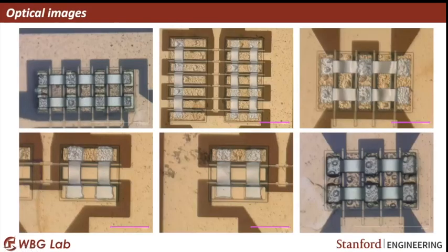Now these are some optical images of the devices we fabricate here. This is one of the fishbone structures, and this is some of the comb layouts, and you can see more fingers here. There are some air bridge connections which connect from this electrode to this electrode. This is just going on top of these electrodes, just shorting these two. This is what I was telling: we do it by different layers, and it takes some time to complete from start to end.